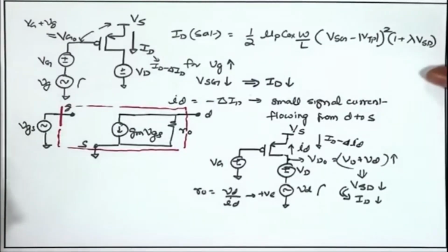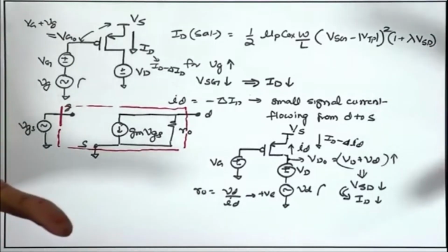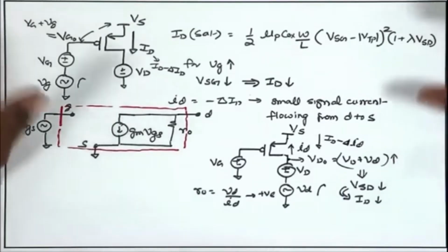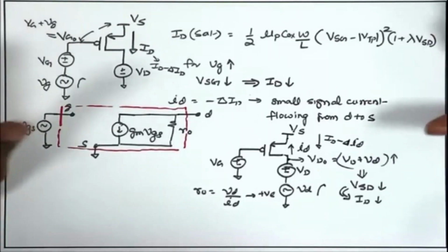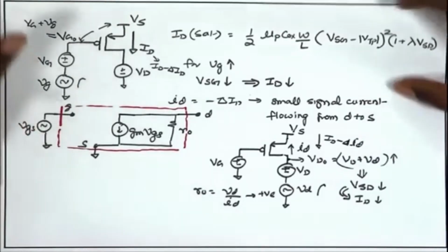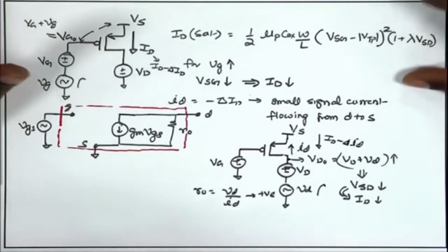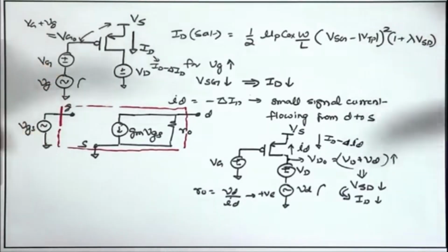So, now once we have gone through the small signal model at low frequencies, that is without considering the parasitics, the next point is to make the model more complete. We are going to add two more features: the high frequency parasitic capacitances that come into picture when we operate these MOSFETs at higher frequency, and the noise component arising from the physics of the operation of the MOSFET.